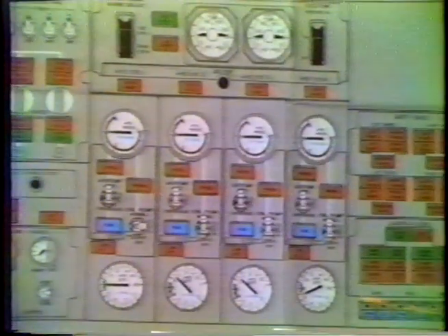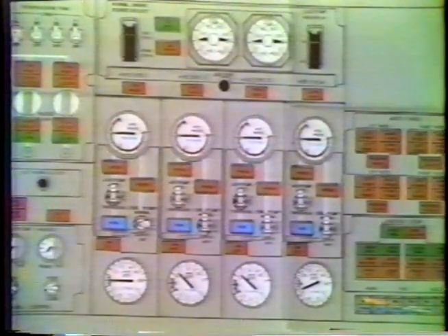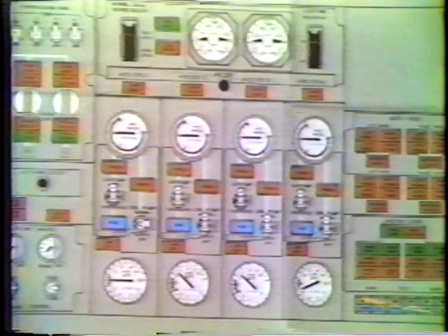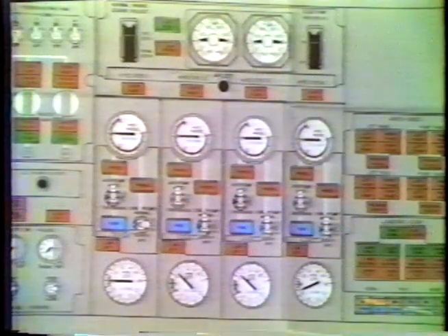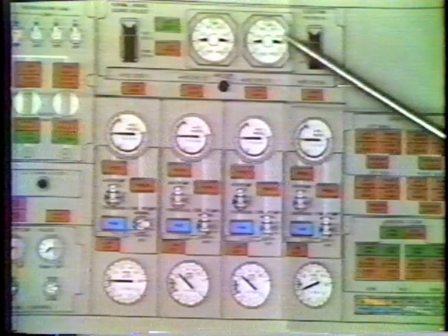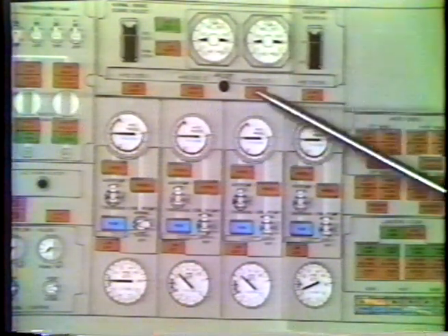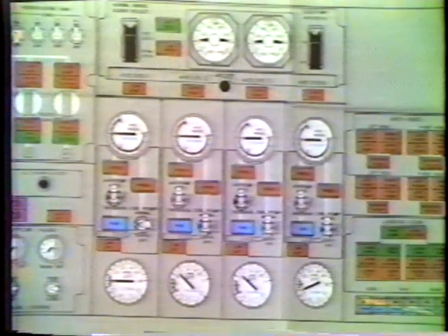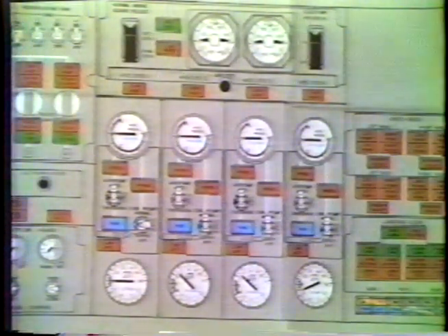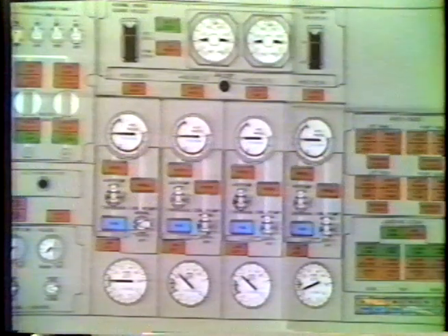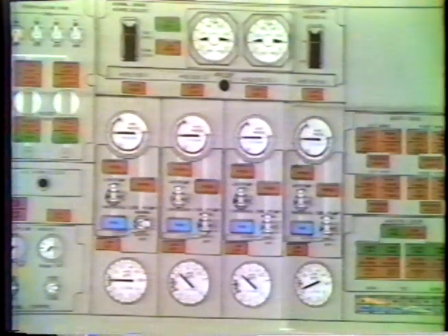I believe that's it on the hydraulic system. One other area of problems in the hydraulic system is the overheat and the temperature control. The overheat and the temperature control are looking at exactly the same position of the system, and what it's looking at is the case drain lines of the hydraulic